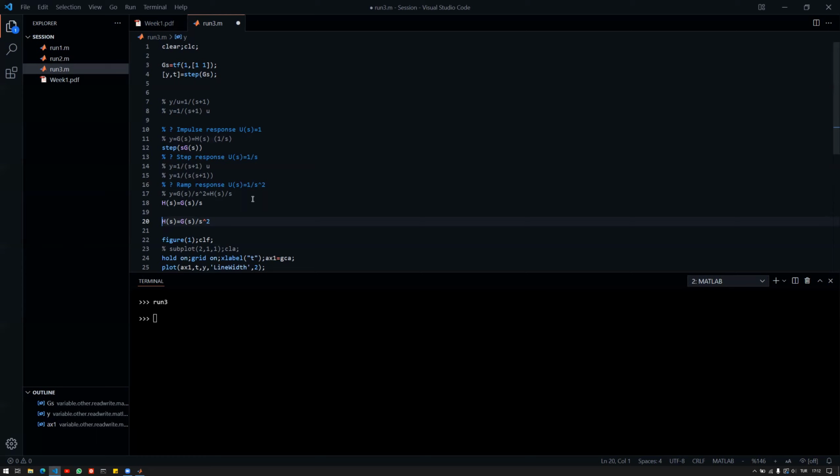So therefore, I can take the derivative of the transfer function, and use the step, so it will give me basically impulse, because times S means taking the derivative. So I'm basically embedding a derivative in there that will take the derivative of the input or the output.